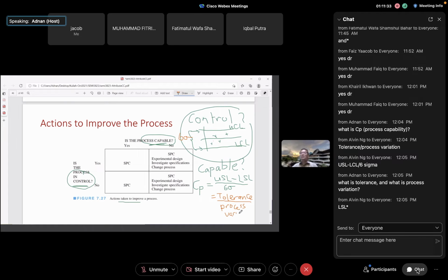So you want to know whether the tolerance that you have picked is capable of being produced or not. Is it capable to be produced or not? Now the important thing is, in control, yes, in control, but if it's not capable, it also has a problem. So the matching between capability and control is very important. Understanding this is the fundamental understanding.